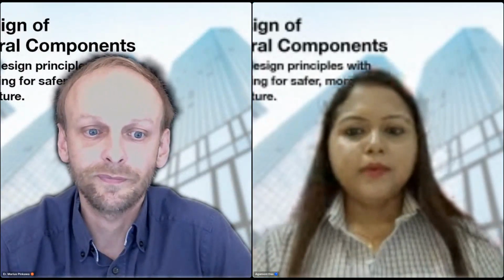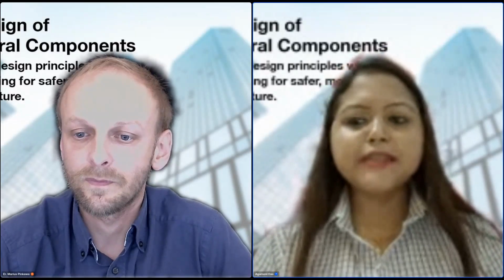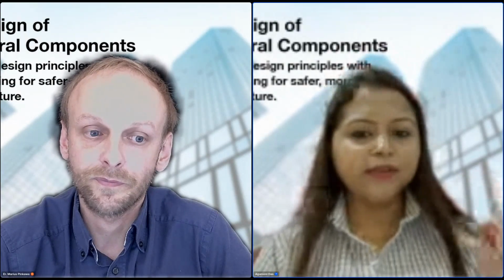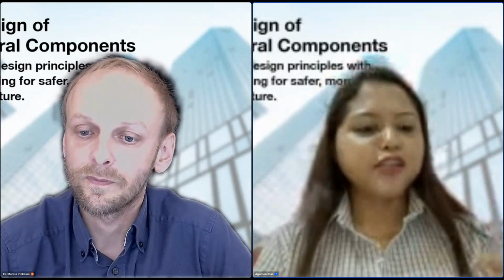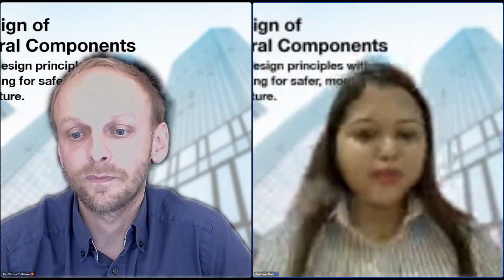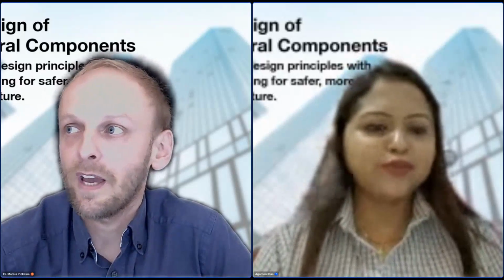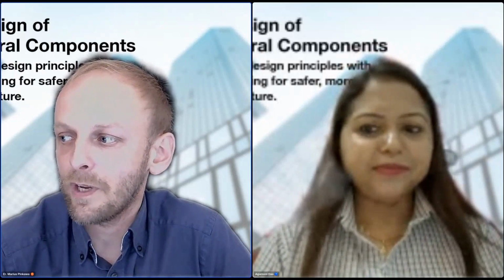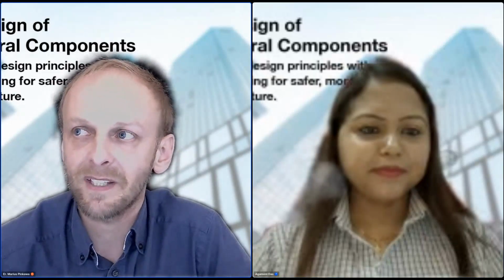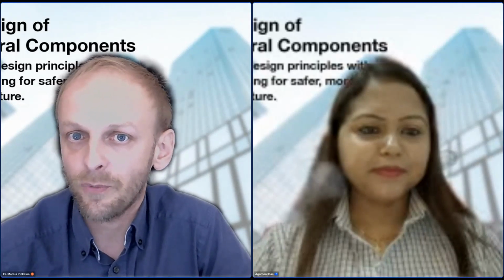Yeah. The next one is: is the design of non-structural components with limited points of attachment the same as that of components with multiple or large attachment points? I think the question is about single-point and multi-point approaches. Okay, so the basic design is the same. We need to calculate the seismic force demand. This is about acceleration sensitivity: the seismic force acting on the structure. So we have to design the anchorage according to the force acting on it.